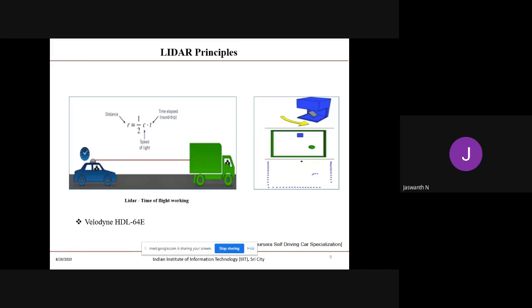Since light travels much faster than the vehicles, it is a good approximation to think that the LiDAR and target are effectively stationary during the few nanoseconds all of this takes to happen. So, the distance between LiDAR and target is nothing but half of the round trip time calculated, multiplied by c. This entire mechanism is called time of flight ranging.